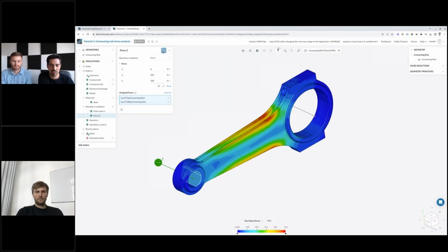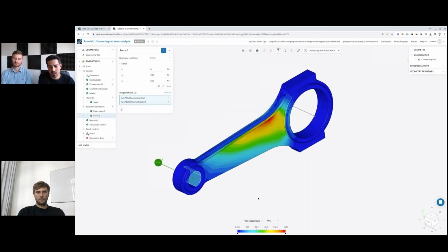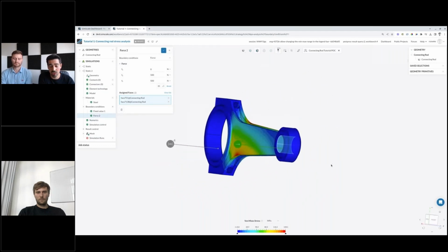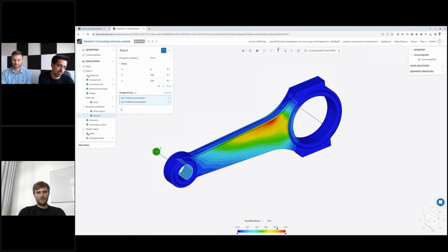And now we can play around with different load cases, for example. So we added a force in the Z direction, and we see a different shape with the von Mises stress, much higher values. Now we're at 150 megapascal. So yeah, we might wonder if the high stress is actually coming from the side force. So we remove the Y force again, run the new load case, and actually check how high the forces are now. Actually, we can confirm on the side force already we get 100 megapascal.